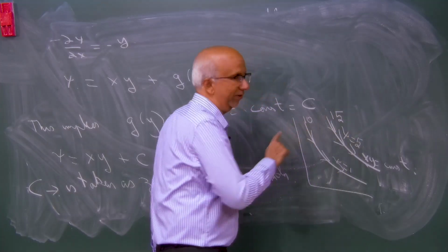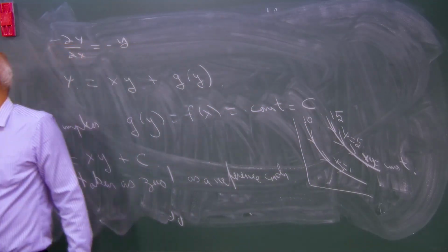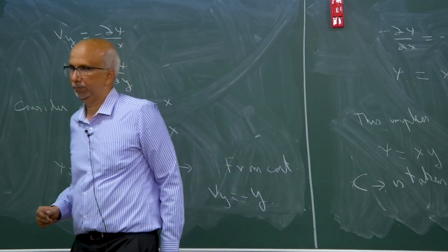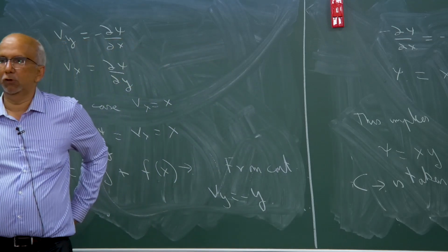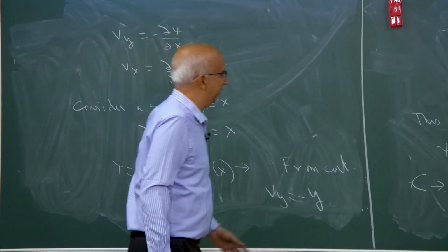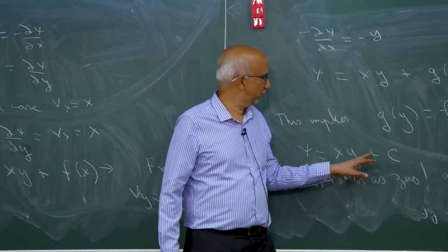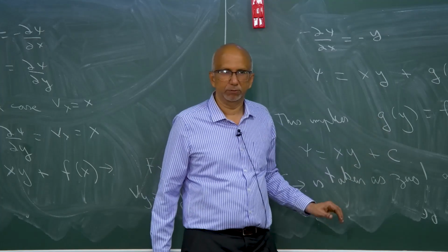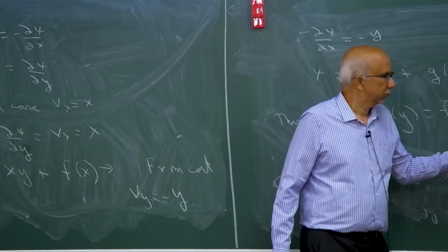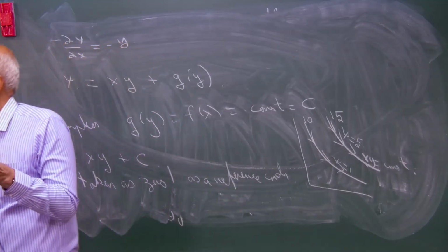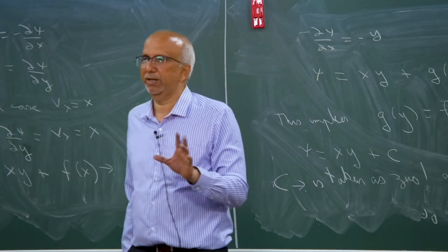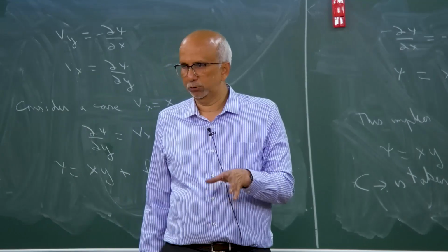So you take the derivative, you will get the same thing, d psi by dx, d psi by dy will be the same. Okay. So that is the reason it does not really matter what this constant is. If you want to take 10, you can take 10. If you want to take a million, you can take a million. But we just want to deal with 0, we just move on in life. Okay. So the stream function is going to be defined within an arbitrary constant. You are free to choose whatever constant it is.